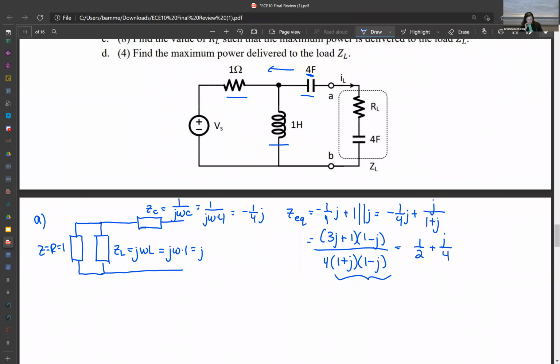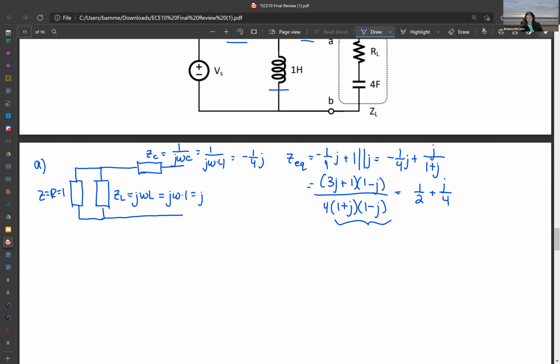Now we found the equivalent resistance, or impedance in this case because we're dealing with sinusoidal steady state, and now we have to find the open circuit voltage. So let's redraw our circuit again. And this time the voltage source that we have in our circuit is going to matter, because when we found the equivalent impedance, we were zeroing out our voltage sources, but now we're not. And so we're going to apply open circuit voltage across this terminal and see what we get.